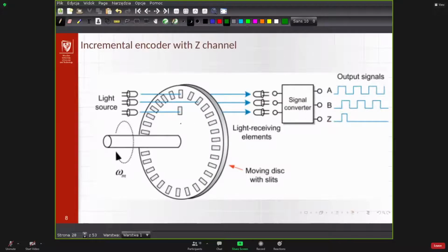When you lose the calibration of the robot, the process is you need to roughly put the joints of the robot in an indicated position, the position indicated by arrows, and then the robot automatically searches for the nearest zero close to this point, and then it calibrates itself correctly.